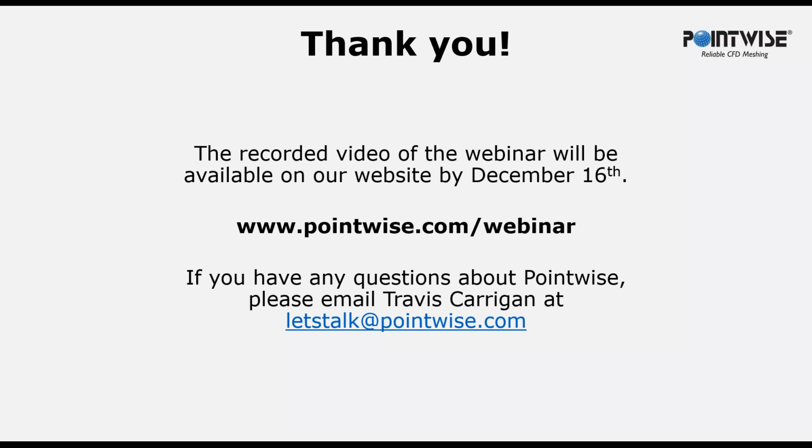heard back from our customers and from some of our own limited testing in-house, the solution accuracy and convergence behavior should improve with both node-centered and cell-centered solvers. Right now, off the top of my head, I don't know that this has been out long enough that anybody has a paper showing those results. This is all what we have heard word of mouth from our customer base. But it should improve. And some of that does have to do with the fact that the volume cells you get with a quad dominant mesh are more flow aligned than with a normal triangular mesh, and that can alone result in some of the improvements in convergence and accuracy.